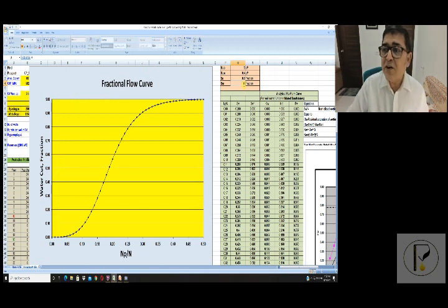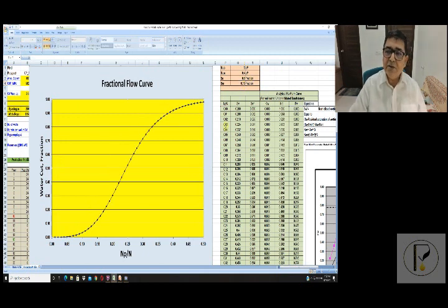See, many reservoirs all over the world are very popular with steam injection of this type of reservoirs, wherein viscosity goes down to a very low number and reduces the SOR to 15%, even lower, 10% or so. But for demonstration purpose, I'm showing just 15%. And you can see how significant the amount of oil is. In US, Canada, Venezuela, China, Russia, steam flooding is extremely popular, and for this type of oil the most successful EOR project has been steam in such reservoirs.